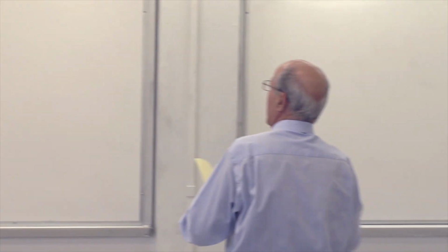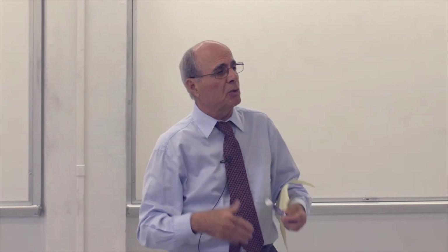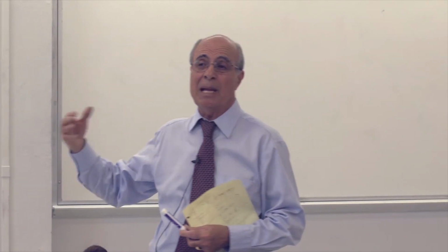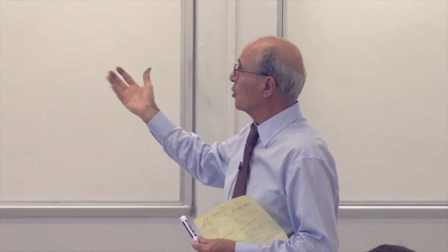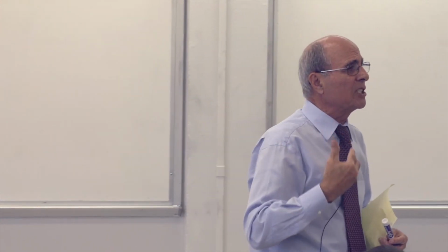Yep. Because it is against the wall, and somehow this rod maybe wants to go that way, I just put the reaction against the action. Because the action is to the right, I'm assuming the reaction is to the left, most likely. I don't know yet. Is that correct or not? But is it the same thing happening at A as well? Yes or no? Because at A also, the rod is attached to the wall. You are pulling it or you are pushing it. There should be a reaction RA.